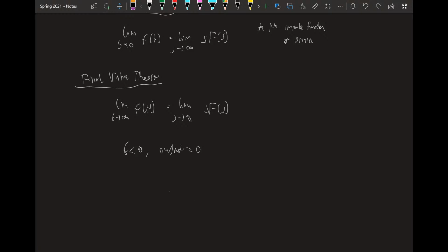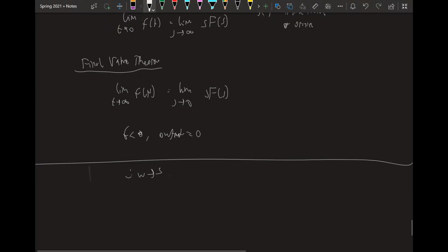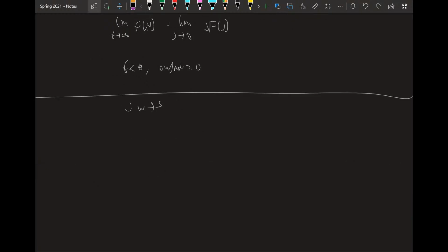So, much like we transformed our circuit components to impedances in the previous topic, you're going to take your components and convert them to impedances again, except this time your variable is s instead of jω. So jω goes to s. And you can redraw entire circuits. Resistors stay the same, but initial conditions are now modeled in the circuit. And this is what I mean.